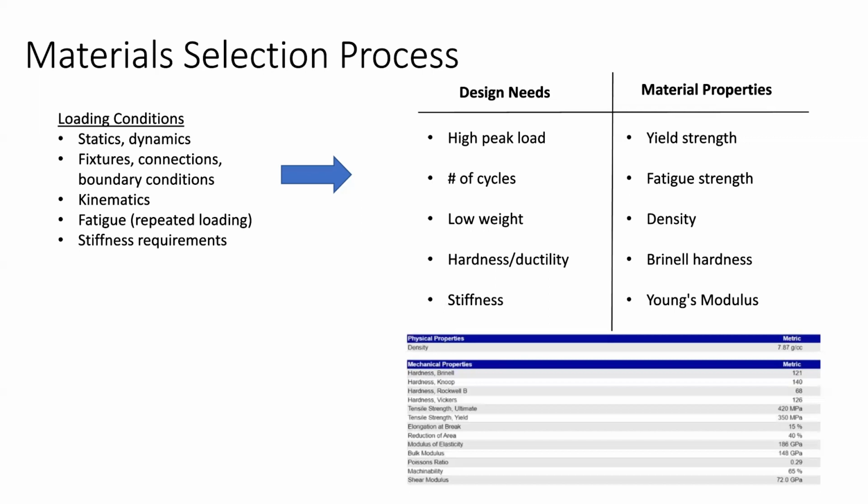And frankly, I don't even know everything about it, but do you remember the broken center lock on the combustion car last year? They used the cotter pin to basically retain the nut. What they didn't realize is they actually preloaded it too low. So the amount of friction wasn't holding the castellated nut on that surface. So part of their torque on the hub was actually being transmitted to the cotter pin, and that sheared the interface where it locked against the nut.